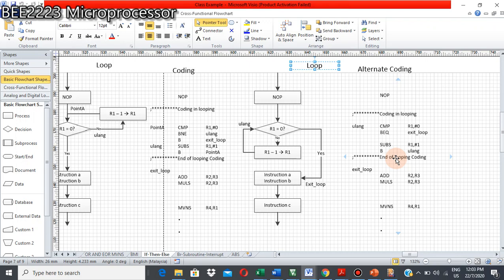So to produce a 1 second delay, we need to design a program so that micro-P wastes 1 million clock cycles, assuming that micro-P only takes 1 clock cycle to execute one instruction.